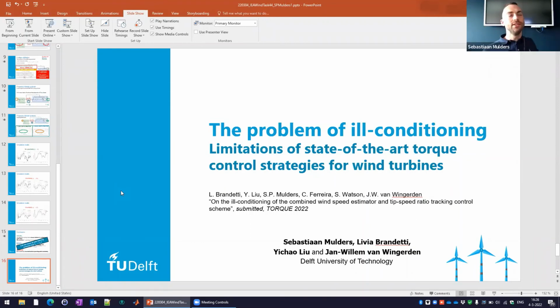Yeah. So the magnitudes 1.2 and 0.8 are just artificial, just to clearly show the implications in the plots I just showed. But it really depends on the type of degradation that you have. You can of course assume that these degradations are really severe in terms of icing. So if you have ice forming on your blades, then you can have a totally different power coefficient curve than when you are in normal operation.